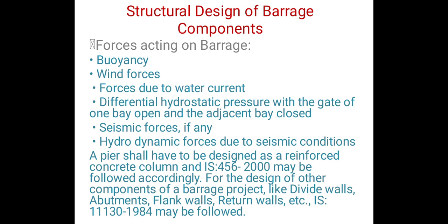Structural design of Farakka barrage components. First one is forces acting on the barrage. First force is buoyancy and second force is wind forces. Third type of forces is due to the water current. Fourth force is differential hydrostatic pressure with the gate of one bay open and the adjacent bay closed. Fifth force is seismic forces, and sixth is hydrodynamic forces due to the seismic conditions.